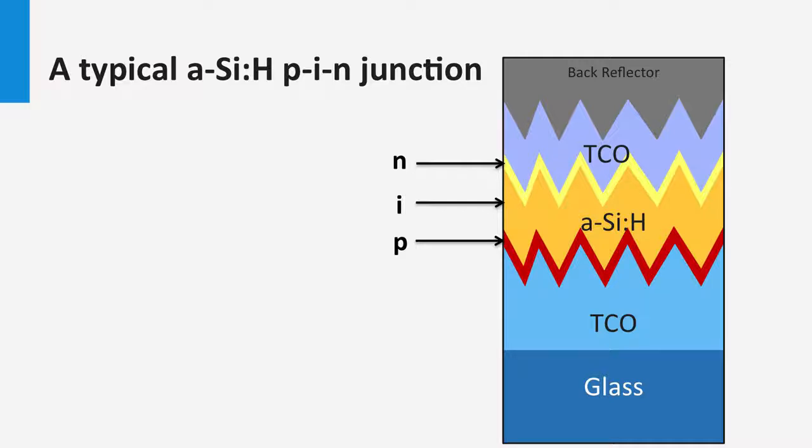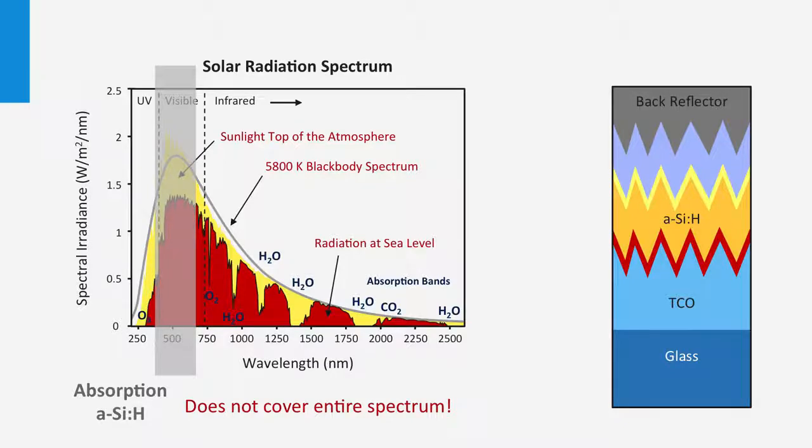As the bandgap of hydrogenated amorphous silicon is relatively high in the order of 1.75 electron volt, it only has a spectral response below wavelengths of 700 nanometers. The best current density achieved in single junction amorphous silicon solar cells are 17 up to 18 milliamps per square centimeters, whereas the theoretical current available in the spectrum is in the order of 23 milliamps per square centimeter, which means that the spectrally average EQE is in the order of 74 to up to 77%.